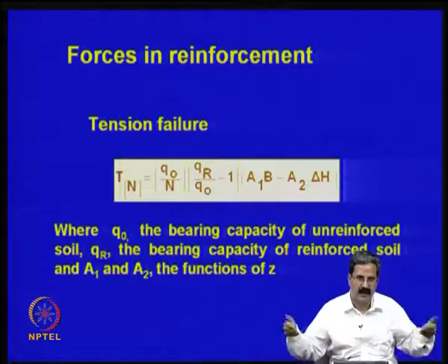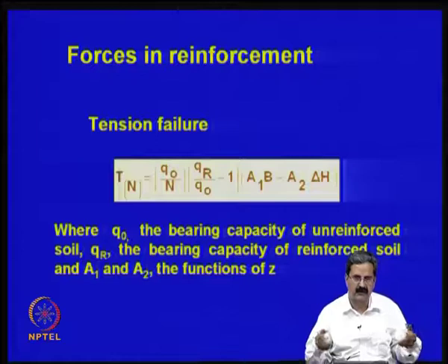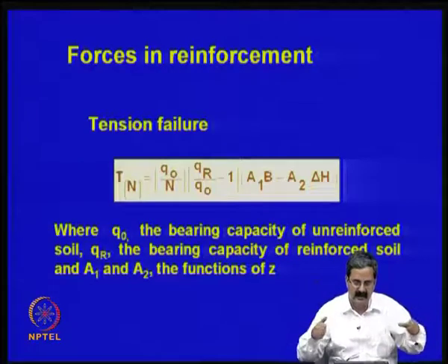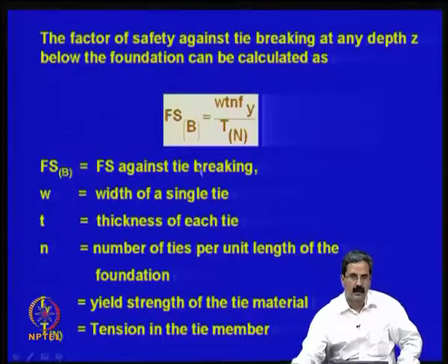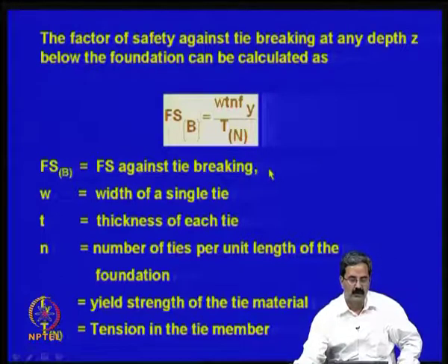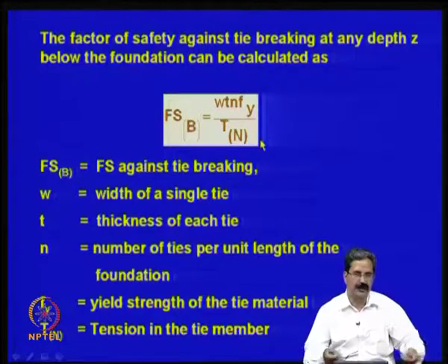Essentially the concept is that you calculate the shear stress distribution, then we make some simplified assumptions, put a roller there, and then calculate, depending on the load applied, what tensile force you get. Okay. Now you have calculated the tensile force, that is fine. Say for example, you take a meter length of geotextile or any material, geotextile, geogrid or something; per meter it has say 10 kilonewtons or 20 kilonewtons or 50 kilonewtons or whatever. Even steel may have higher tensile force carrying capacity, right.